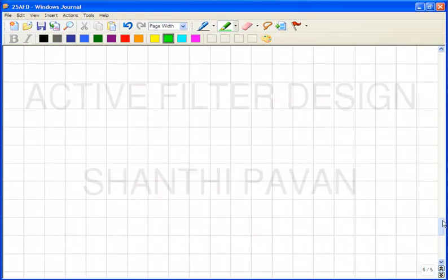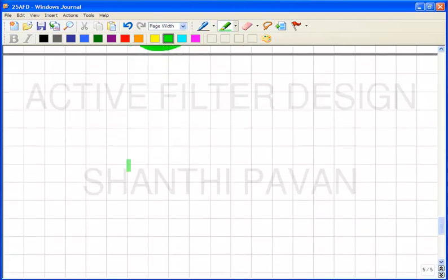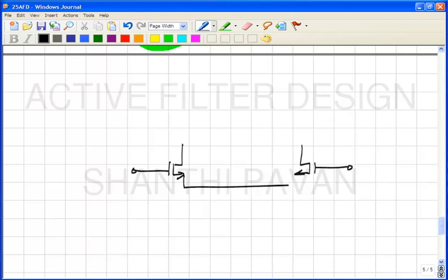The next thing to do is to figure out, are we done, or do we need something more? Anyway, as an aside, how do you think I'm going to implement the tail current source? So you put a current mirror of sorts and you're done. So this is VCM plus VD, VCM minus VD.